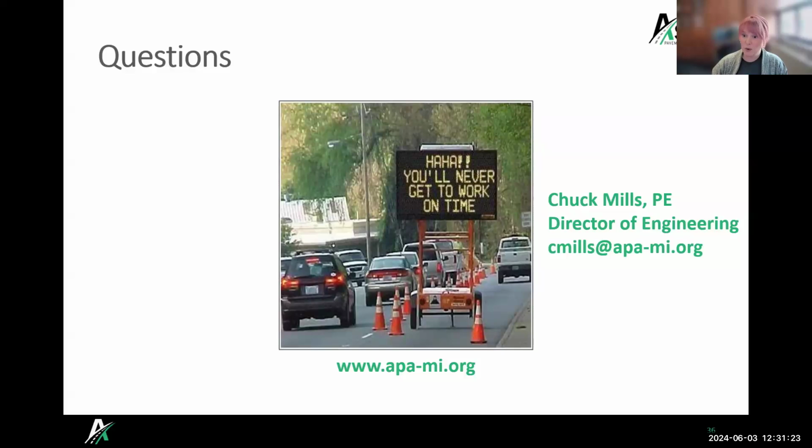Speaking of parking lots, we do have a question about parking lots, which was if you're paving a parking lot or a small road patch, what mix should you use? Which I think we just answered, but for both lifts, would you be using the same mix for both lifts? Yeah, I would say whenever you can, use the same mix for both, especially for patching. Typically, if you're doing a bunch of patching on a job where you've got a bunch of mix, use that same mix.